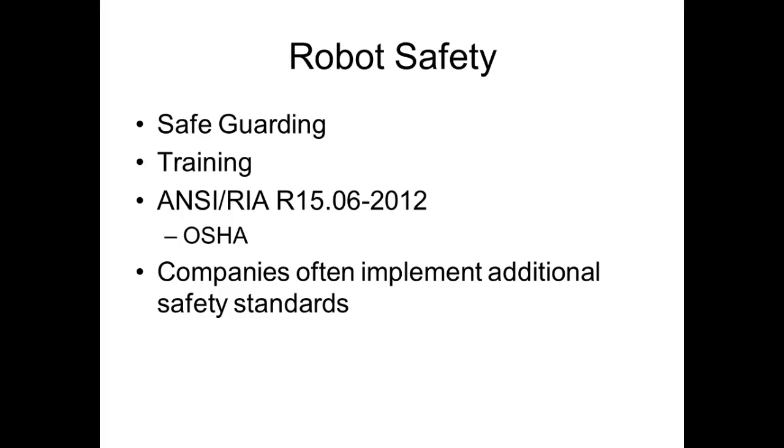Most electricians find out that it's common sense, you know, that there are some things that are not in the National Electrical Code that are accepted by the authority having jurisdiction. I think the city of Birmingham's inspection doesn't allow you to put more than 15 units or plugs on a run. That's not in the National Electrical Code.